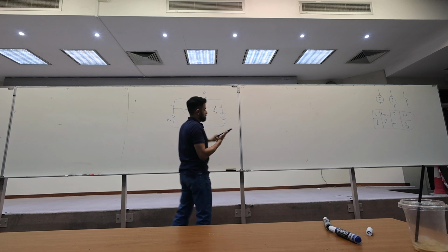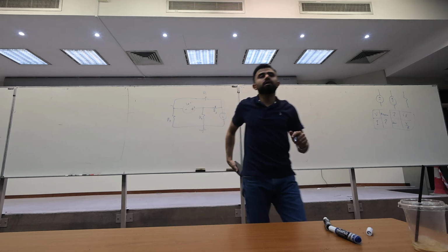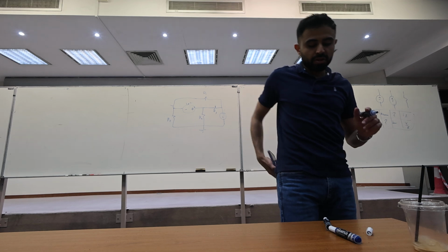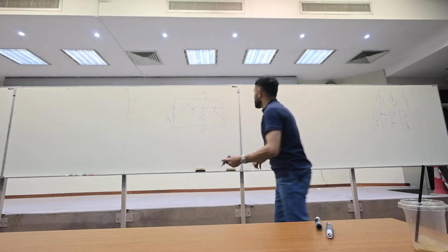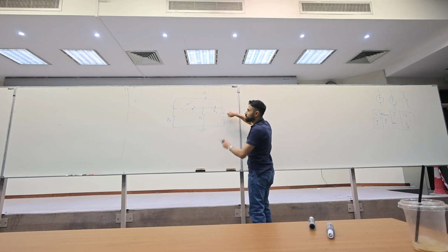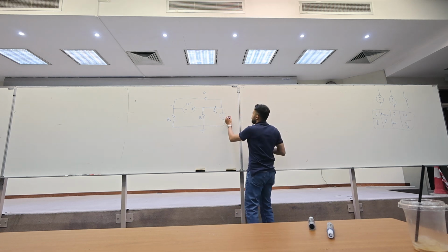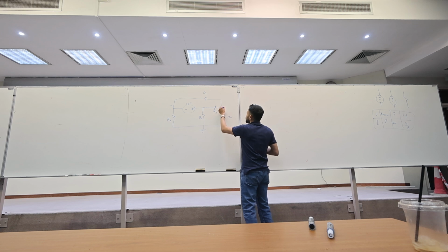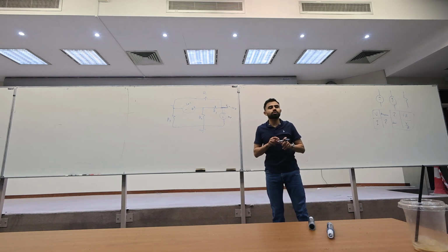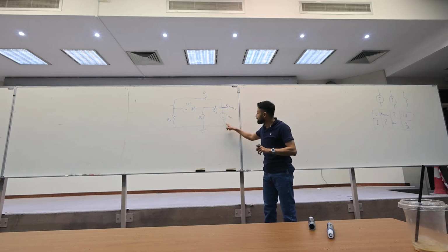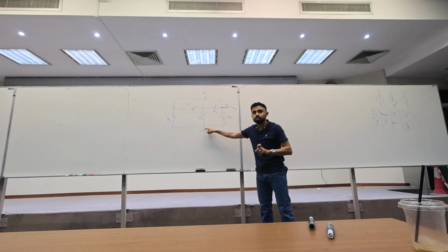Okay? What did we say about the supernode? First of all, you have to understand, because the battery is flipped, what was the voltage? 15? I think 15. So 15 volts here. What is the voltage here at this node? It is V3 equals minus 15 volts. Now, in the past I told you at node voltage analysis, if you have a voltage directly connected to the ground, yes.